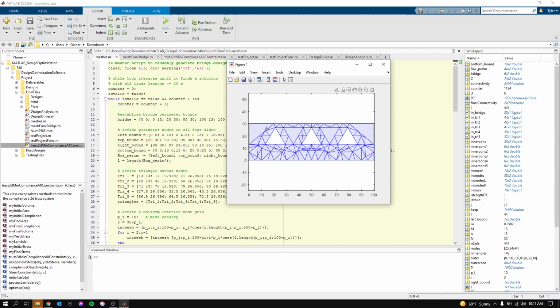You can see kind of the hard-coded perimeter that we're always going to get. You see the blue space is our operating space where trusses are allowed to be created. White is void space, so we can't go in these void spaces. You'll see these additional triangles here, so we created additional void space to mimic that Warren-style truss and give some more material that can be reallocated to other members. You'll see the symmetry. The random design is mirrored horizontally across the center axis, the central y-axis here.